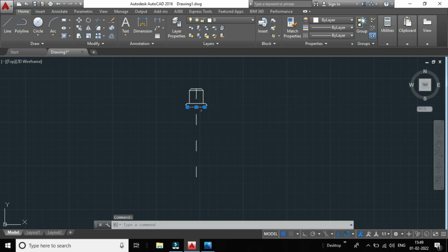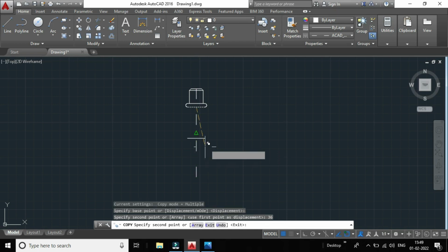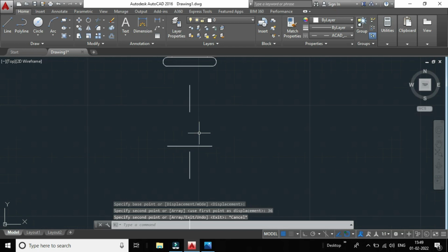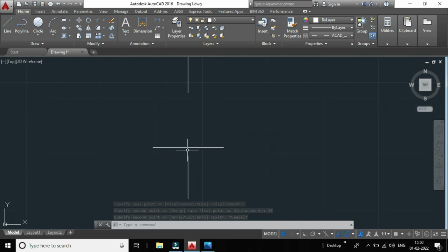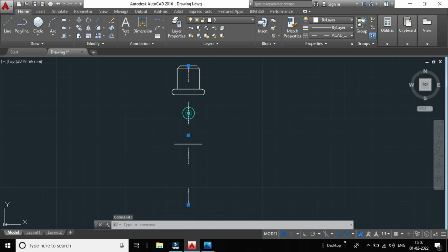Click on the center option here. So here it has been given. Next we are going to draw the line. Click on this line option here. After clicking the line option, from this end point we have to give the distance of 4 downwards. Click on this 4 option here, click on escape here.